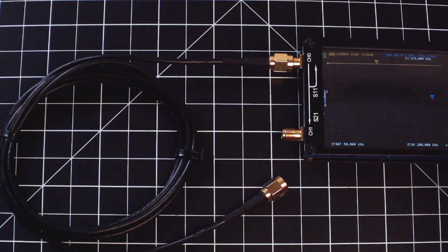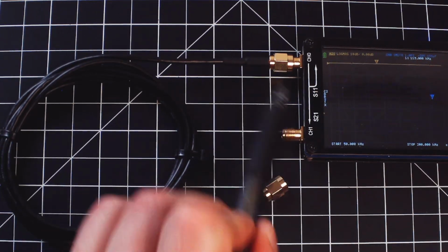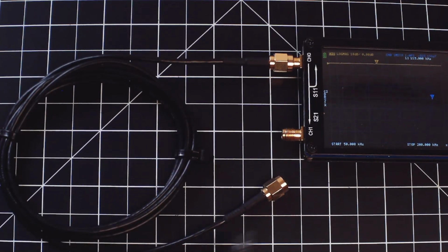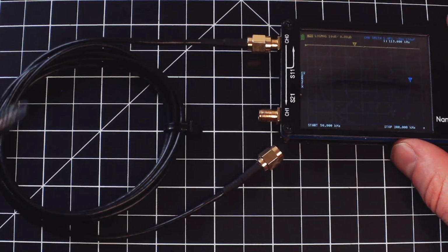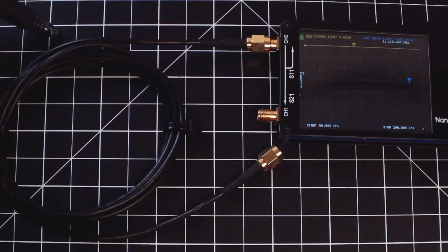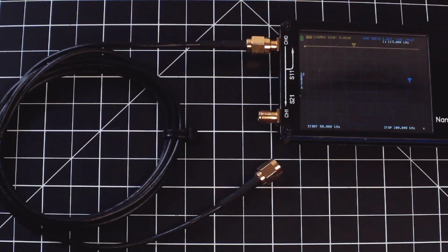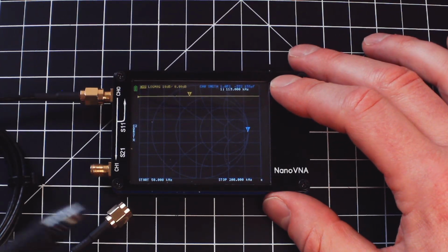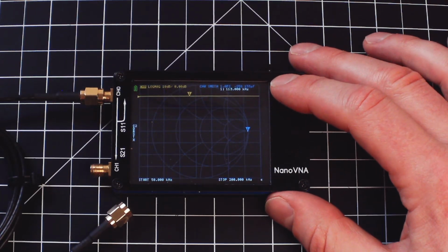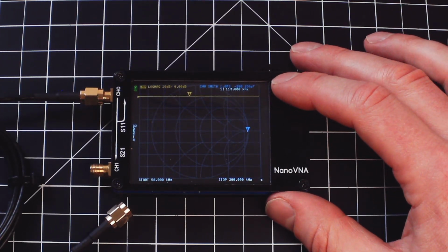But the frequency is so small, that means the wavelength is gigantic. Therefore, the phase error that accumulates from this back and forth propagation is essentially negligible right now. Okay, so we can pretend that that is basically zero, which means all it is seeing is the equivalent capacitance of this lump of cable here, which it calculates for you automatically on the Smith chart. And if you look very closely, it's coming in at about 155 picofarad.